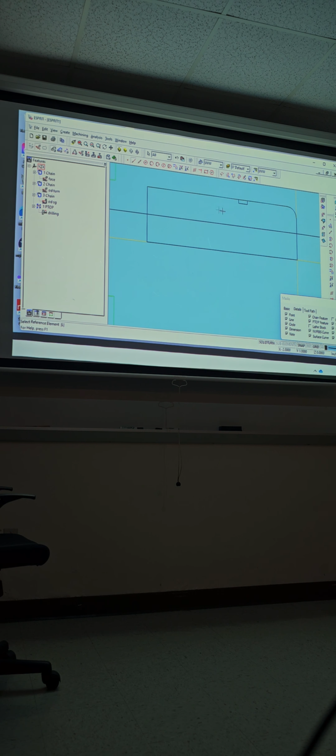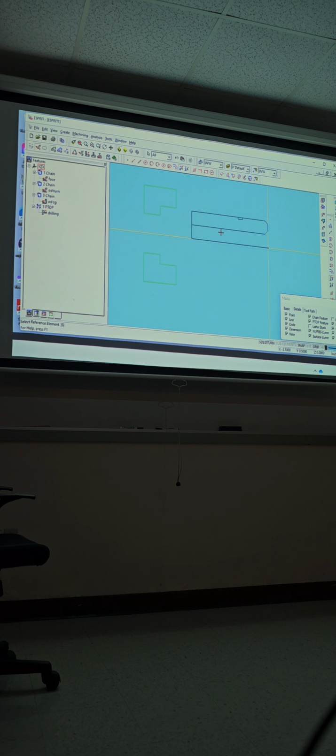What else do we need over here? You need a chamfer. So we're going to go 45 degrees, angle chamfer, distance, let's say 0.200 by 45. Bam, bam. Very cool. Horizontal. There we go. Then don't measure, keep the chamfer where this drill hole is. 0.200 by 45 degree angle. That's a standard. A 45 degree angle is a standard chamfer.